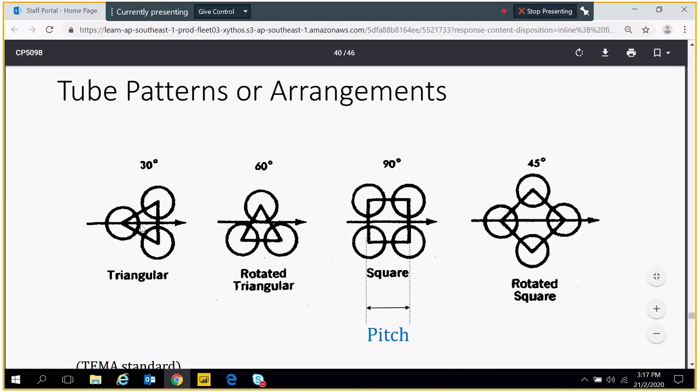Right. We have fouling. How do you get rid of the fouling? You have to mechanically scrape off the fouling on the surface. You can use a physical method, or you can use a chemical method to clean the outer surface of the tube.